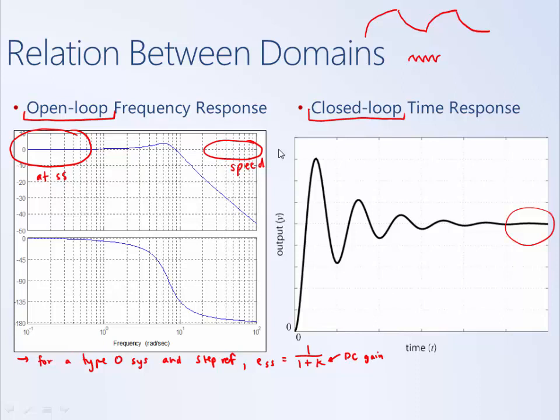Now let's think about what would relate to overshoot or oscillation. So one thing that you might recognize is basically how big a system's resonance is. If it has a large resonance, that indicates that the system will have more overshoot. Furthermore, if a system overshoots a lot, it tends to indicate that it's not very stable.